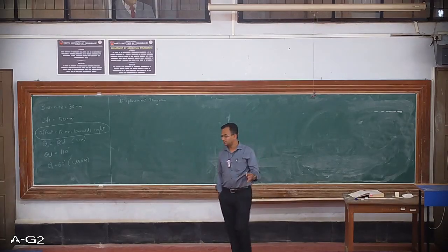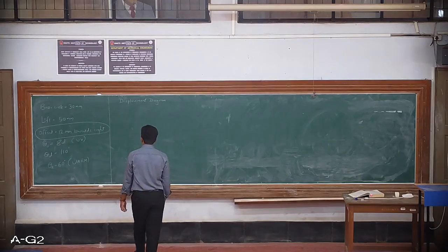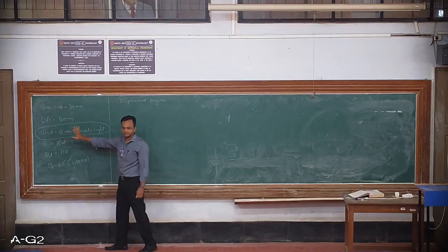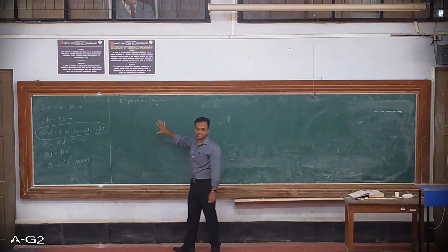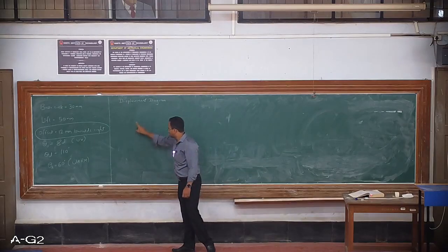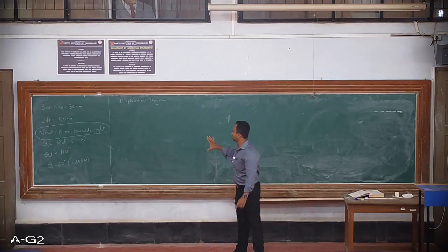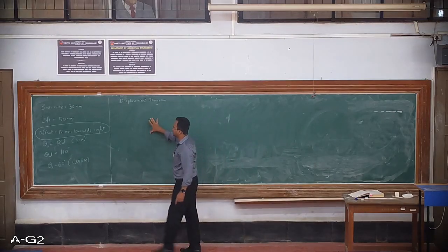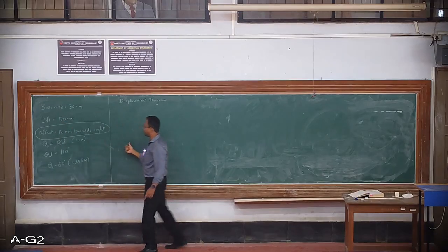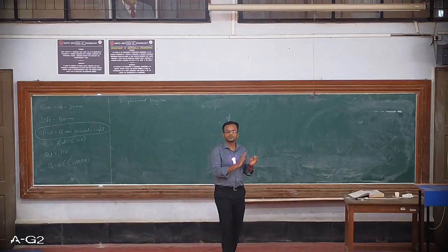So as I have discussed in the previous lecture, irrespective of whatever is the problem data, few initial steps of drawing the displacement diagram will be same. That means I have to start by drawing a rectangle whose height will be equal to the maximum lift, that is 50 mm, and width of the rectangle will be equal to appropriate length of 360 degrees.